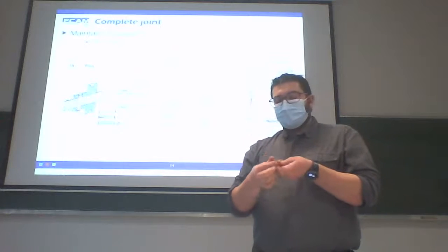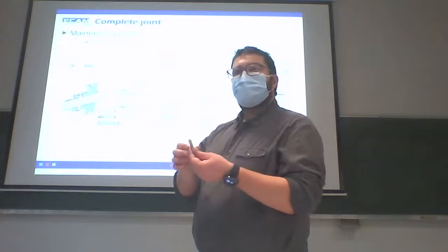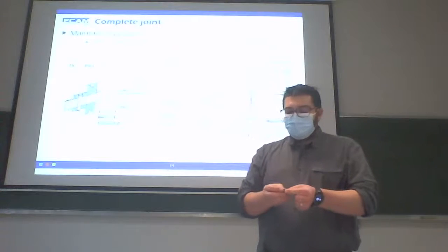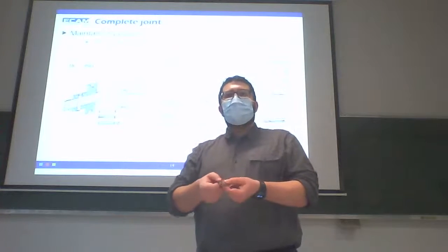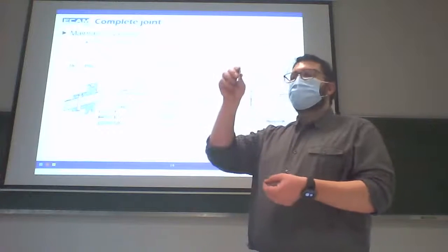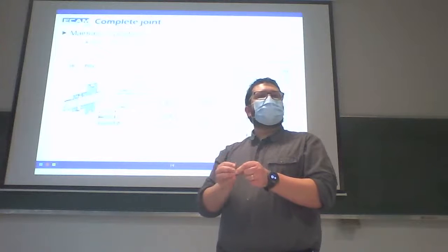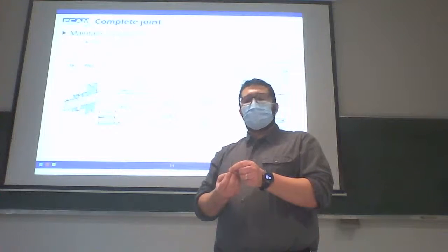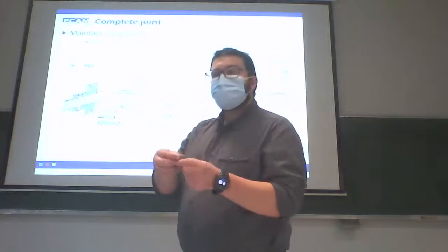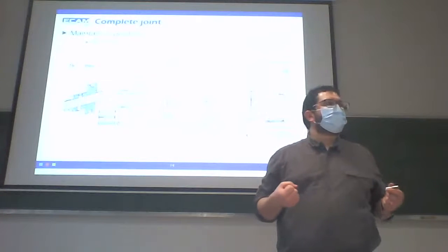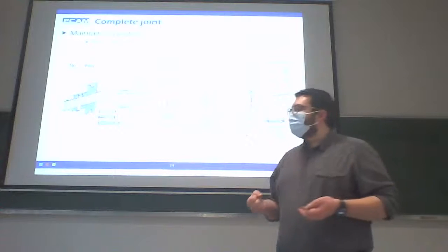The size of the pin is bigger than the size of the hole, but we have an important chamfer. And when we put the pin inside of the part, we'll close the groove to reduce the diameter of the pin. But because the metal of the pin is elastic, it will try to reopen inside the hole and maintain in position like this. Okay?